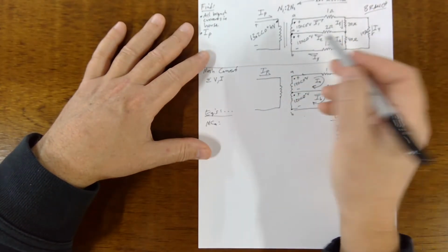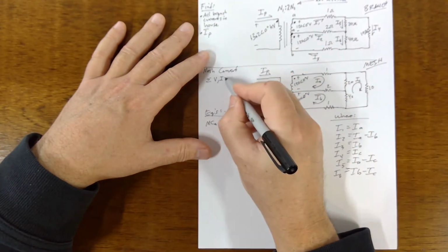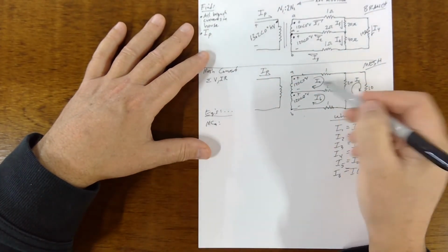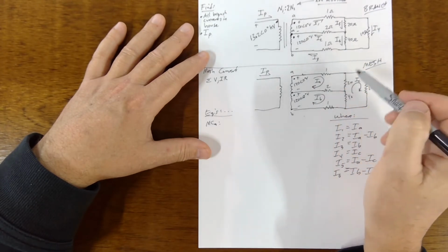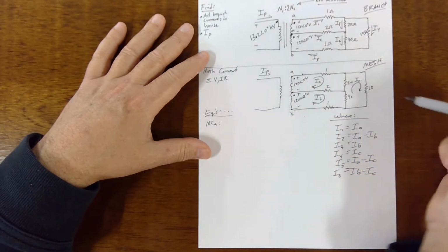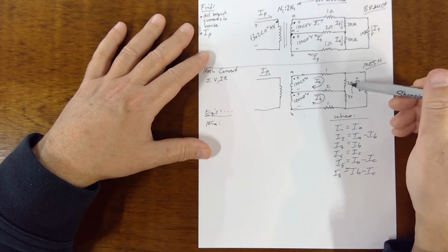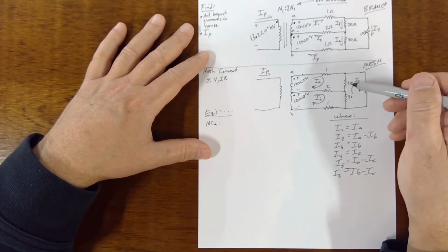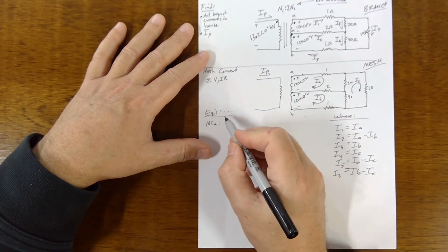These are all resistances. The Z's are the R's. You could say IZ, you could say IR, because we're just dealing with resistance here. There's no capacitance in this model. Although in a real house there would be. Every electric motor you have in your house has inductance, and some devices have capacitance in them.